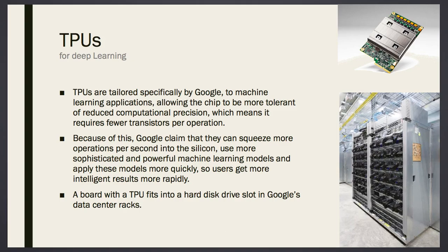But if you go to more aggressive quantization levels like 4 bits, you lose many things. But at 8-bit quantization, you don't lose much with dynamic range. That was the outcome of the papers we have discussed. Knowing this, Google designed their TPUs for lower computational precision as well. That's how they could surpass the GPU performance.